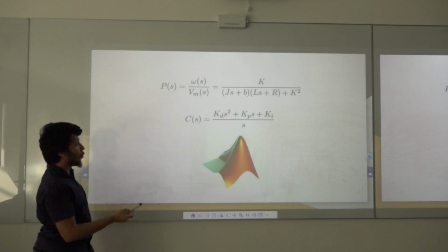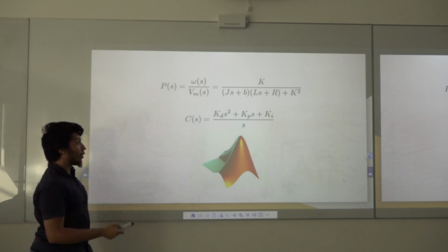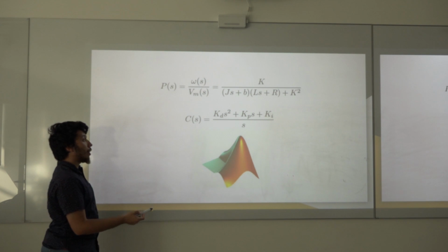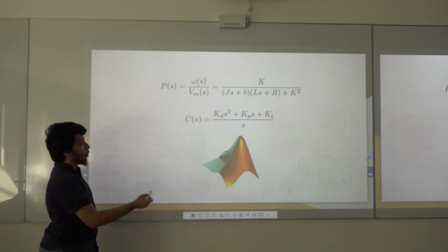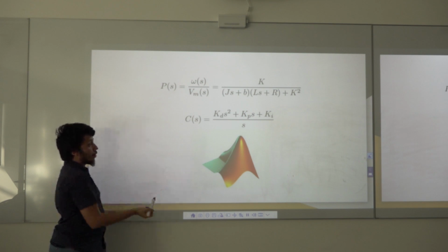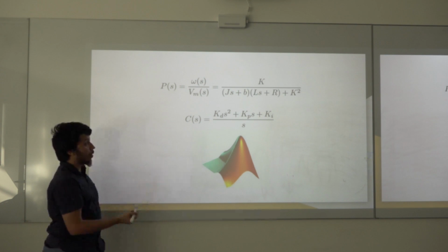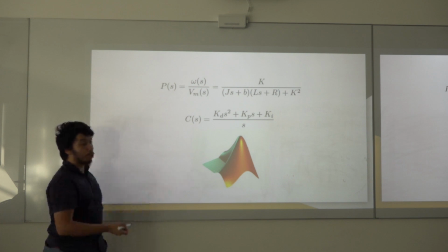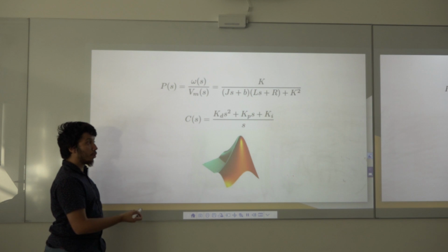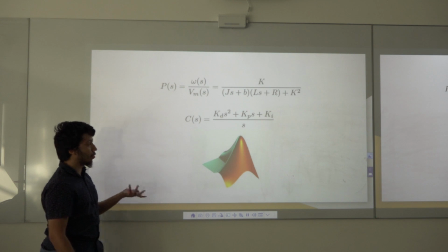Lastly, our controller of choice is the PID controller. The PID controller has benefits that come in its parts. It consists of a derivative portion, which helps with the transient response of the system, improving on the speed and response time of the system. It also consists of a proportional portion, which helps with the stability of the system and helps manage the overshoot of the system. And finally, an integral portion, which ensures that the input and output are one-to-one, essentially reducing our steady state error to 0.